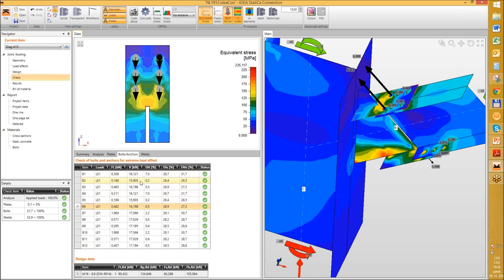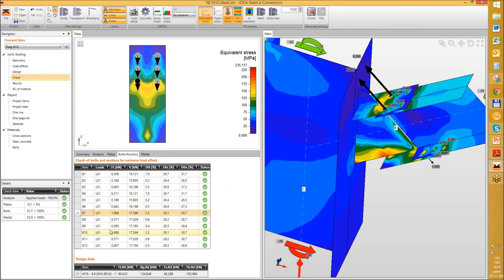You can see that the distribution of shear forces is, in fact, like the average value. If you divide the force by 6, you have 16, 15. It's almost 16 everywhere. So these values are calculated thanks to these contact elements and thanks to our special model around the boreholes. The results of shear forces are quite nice, I would say.